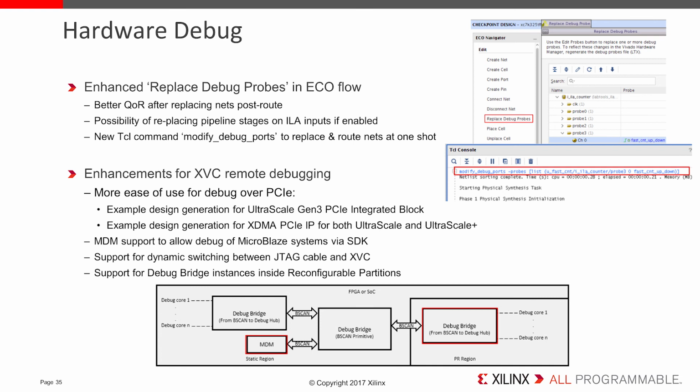The same support is also added for the UltraScale Gen 3 PCIe block. Support for MDM is added to enable MicroBlaze debug via SDK using XVC, and new support of switching between JTAG cable and XVC along with fewer restrictions in PR flow.